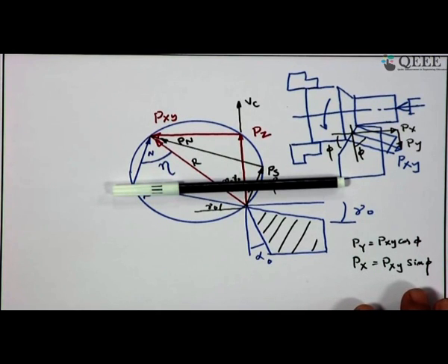So, in that case Py should be very small, and how to make it happen? These two equations give you that answer. Phi should be as large as possible. If you have phi 90 degree, Py component vanishes. So, it is only Px. So, with Px you have thrust on the bearing, but no thrust on the job.